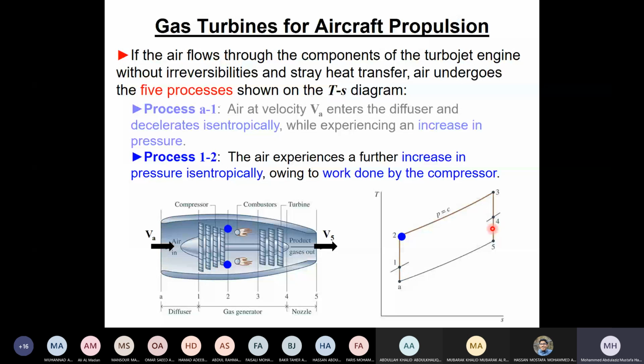So we start from the enthalpy. When I say H3 minus H4 equals H2 minus H1, it's wrong to say delta T equals delta T unless I say that Cp is constant. So for the case Cp is constant, you can say T3 minus T4 equals T2 minus T1. So the answer to your question is we must calculate the enthalpy unless we assume that Cp is constant, then we do not have to calculate the enthalpy.